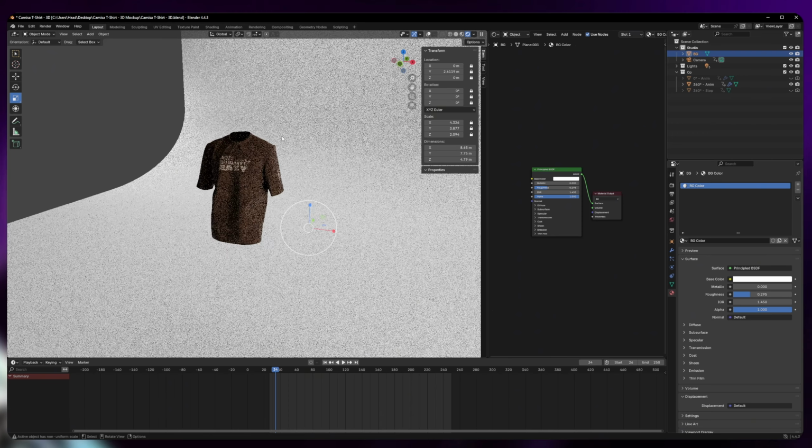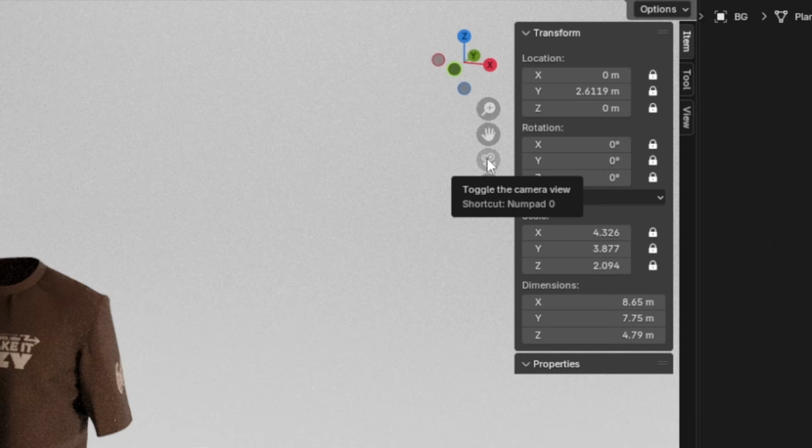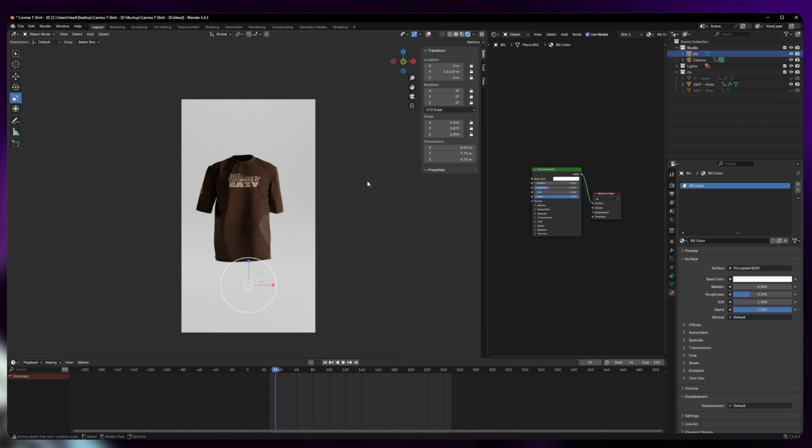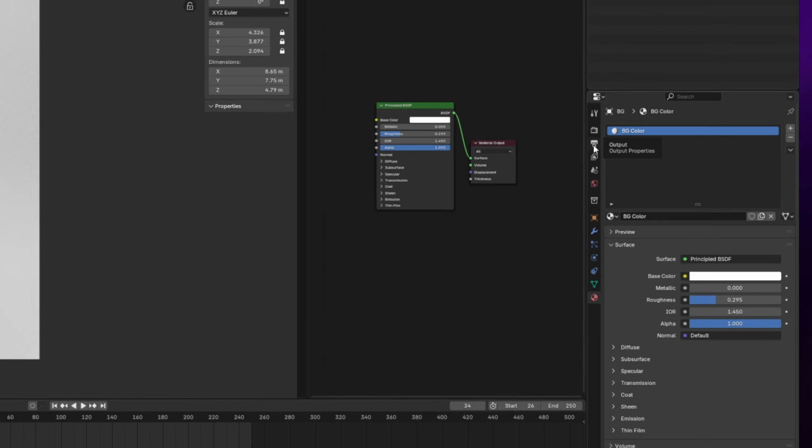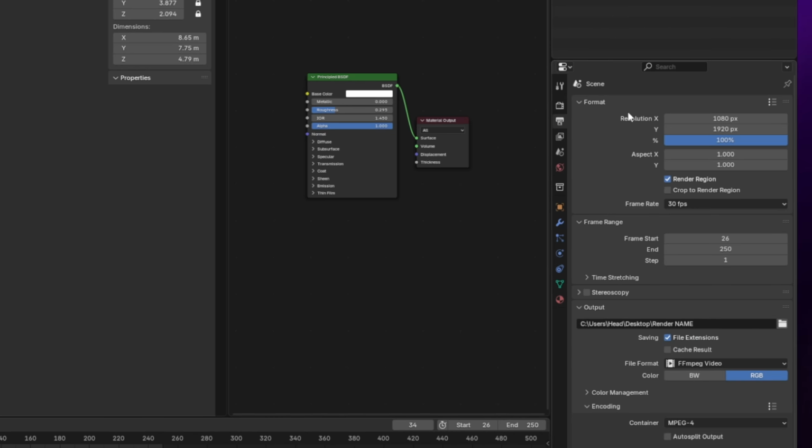Here also an additional thing. You can click on this camera here on the Blender to go back to visualization. Where will it be rendered? Let's configure where the file will be saved. You will come to this third option, the file output. Here you can configure the file resolution size. It is already configured for social media, vertically. If you want, you can change it. Just set the size in pixels here. So here, in 1080 by 1920, we will click here on the file output.